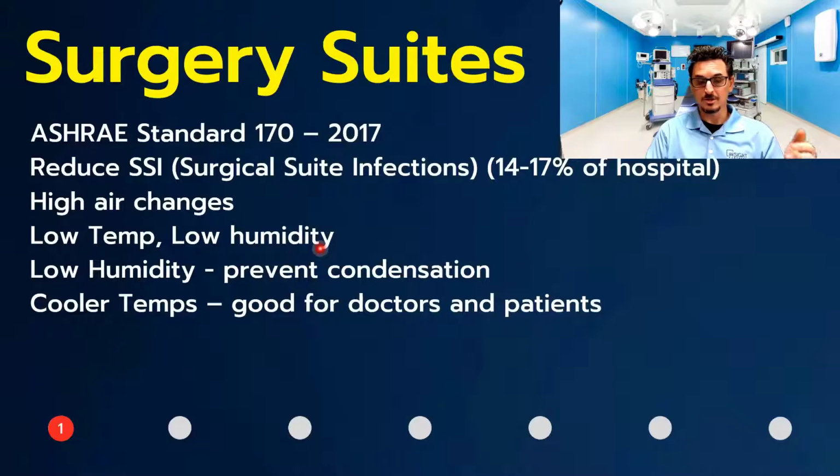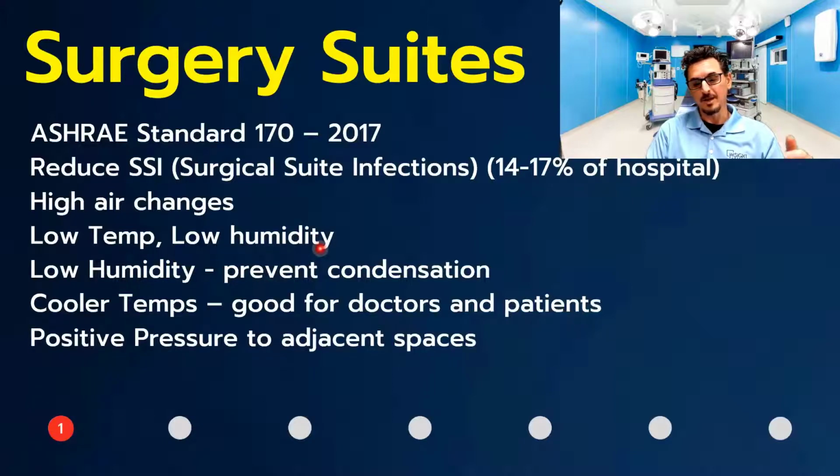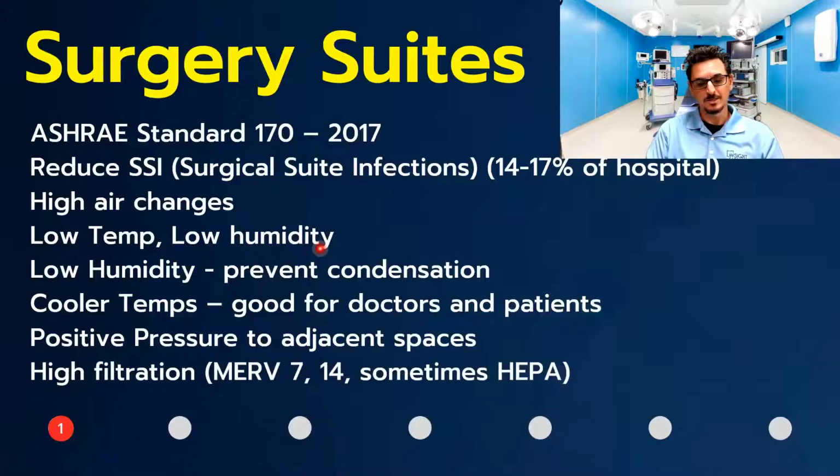Cooler temperatures, good for the doctors. It prevents them from sweating. It's also very good for the patients, I found out. I read that yesterday. I didn't know that. It has to be under positive pressure to adjacent spaces, and a high level of filtration is required, MERV 7, 14, and sometimes HEPA.